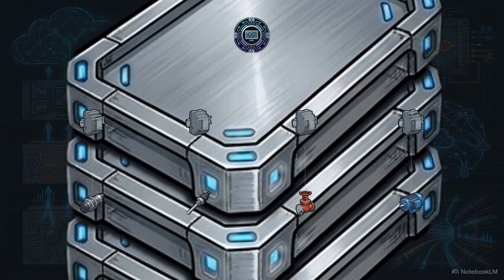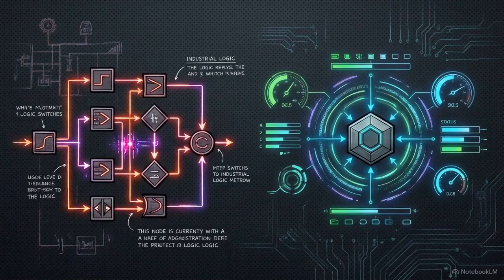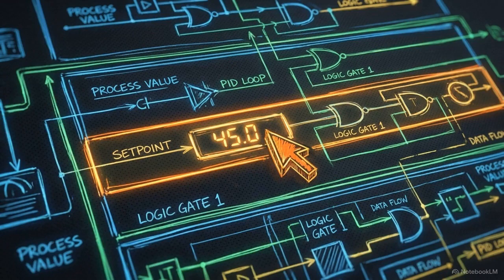As we step up to the third level, we shift focus from localized machine control to macro-level facility oversight. This is the SCADA layer. While a single PLC has a narrow focus, the SCADA system provides a broad, facility-wide view, aggregating multiple real-time data streams. SCADA's primary function is to aggregate the data from hundreds of individual PLCs and present it within a unified monitoring interface. Through this interface, operators can monitor entire production processes, track critical alarms, and adjust operational parameters without ever